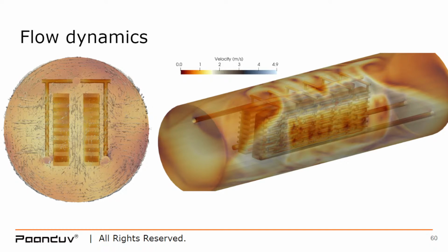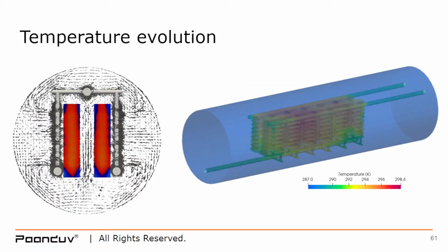So the fans are throwing the hot air out, away from the servers. Some of that air rises up, some of that air cools down, drops down again, and recirculates because of the cylindrical nature of this data center. And if you look at the temperature evolution, you'll see that towards the outer sides of the data center, it is cooler compared to the central part, where there seems to be a dead zone for temperatures.